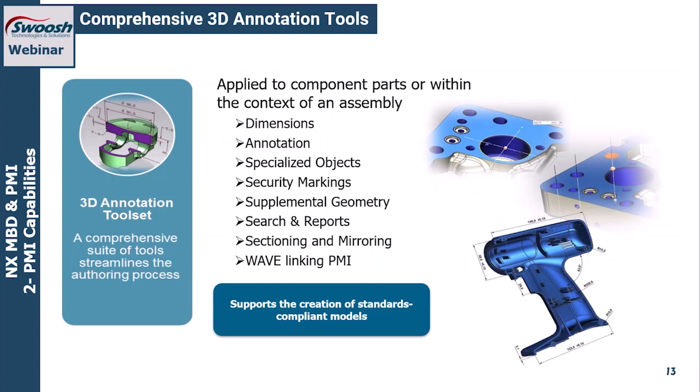All right, so looking at the annotation tools within the PMI toolset here, if you think of applying PMI as being very similar to creating a drawing or a traditional drafting practice here, you're going to have all the same tool sets, so we can create dimensions, annotations, specialized objects, security markings, supplemental geometry. We can create searches and reports. We can do sectioning and create lightweight section views of our parts to go ahead and detail the internals of the part. And we can also take advantage of a mirroring functionality as well within the design environment. And finally, we can wavelink PMI and reuse that PMI inside of other part files.